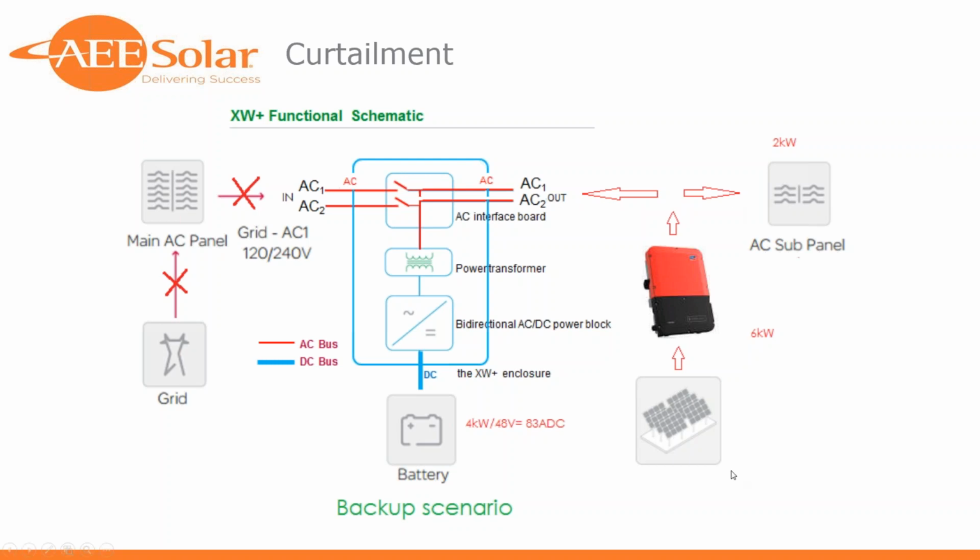I've got an AC grid that's... Sorry, let me take a moment to make sure that this is clear and I describe it accurately. The battery's filling up. I've got excess power on this AC bus, because I've got minimal loads, being that it's noon. What do I do? The power has to go somewhere. I can't just turn it into heat. My choices are, the choices on the XW plus or the Radian or whatever you have are very limited.